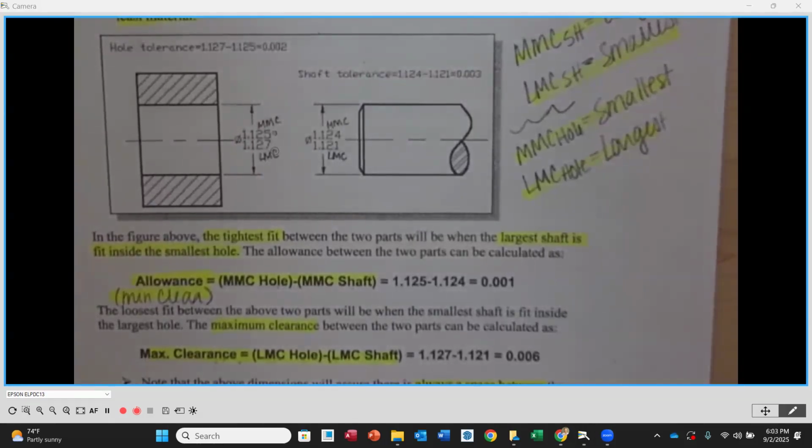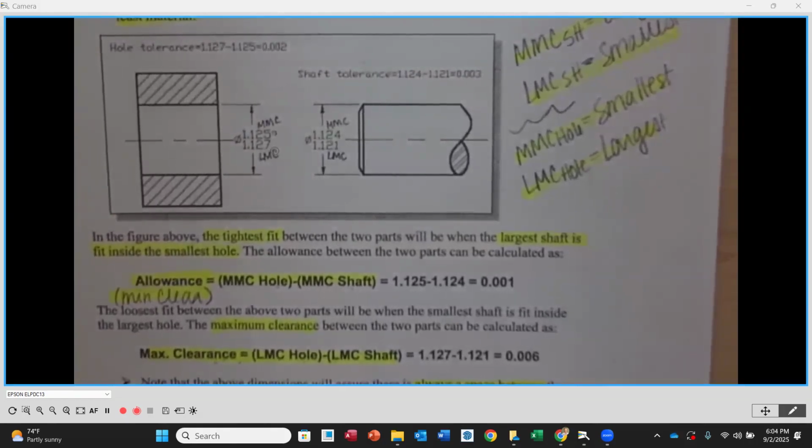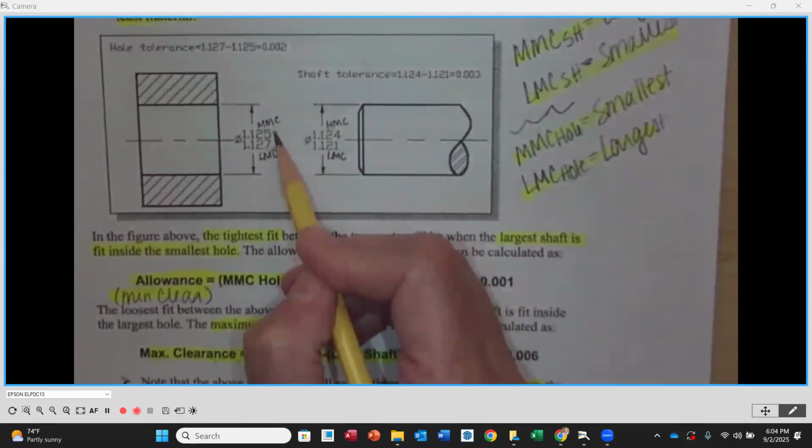The drill physically is getting smaller, but the chips that we're generating are getting more coarse and they're actually boring out that hole at the same time. So the natural effect when the drill dulls is that the hole is going to get larger. Okay. That's why we see that. Now, am I going to look at your hole sizes and say you should have that there? No, but you may see that in places. And in this case, that's why it is on top.